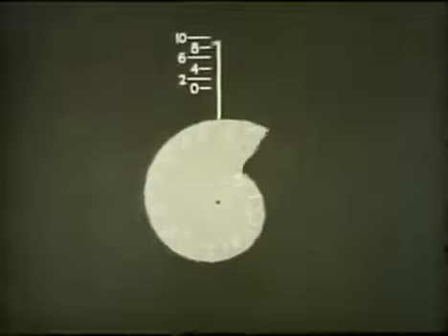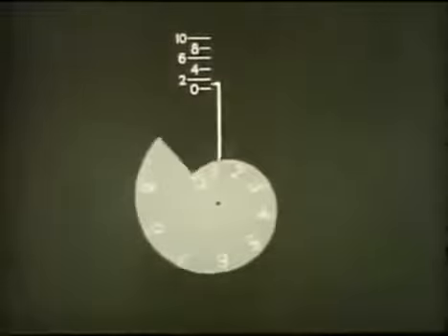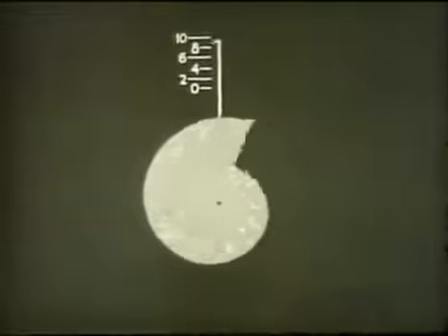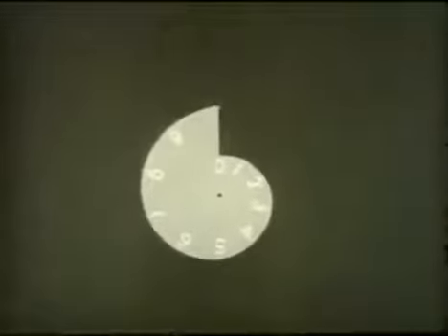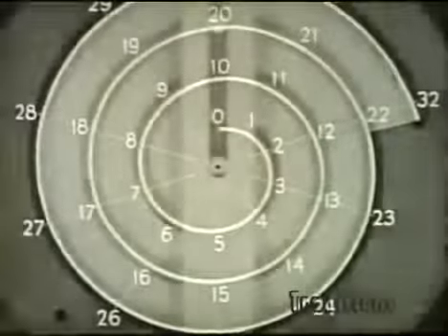With an outside shape as the working surface, the capacity of such a cam is limited to 1 revolution. Additional revolutions can be obtained by extending the working surface, which now must be a groove. An example is the constant lead cam, where the follower is a pin riding in the groove. In a fire control computer, a rotary input of ship's speed is delivered as linear motion of the follower.